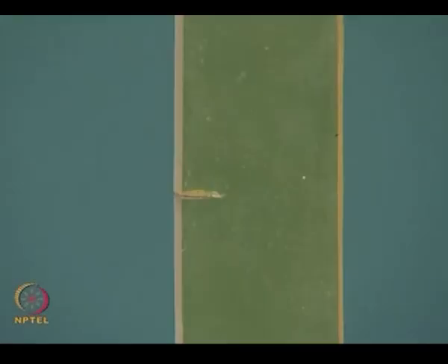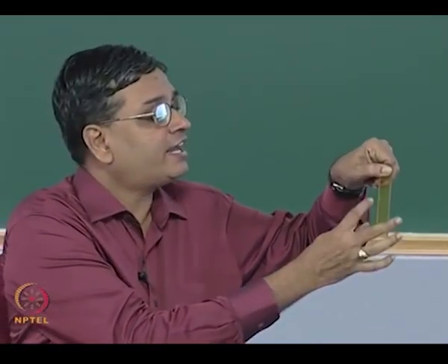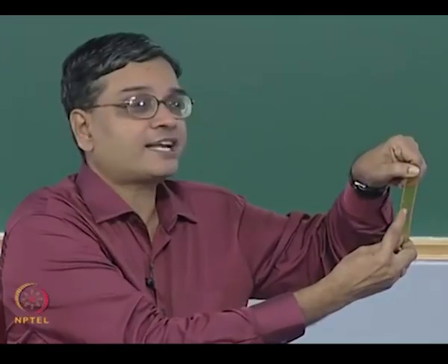If you take a tension strip and then pull it, you would really not recognize the change in thickness that much, because the stress levels are reasonably small, the strain is going to be much smaller. On the other hand, if I have a specimen which has a crack, because of very high local stress, you will find near the crack tip a dimple would be formed. That is because of the lateral strain. Lateral strain cannot be ignored, and you have the dimple formation in the zone near the crack tip.